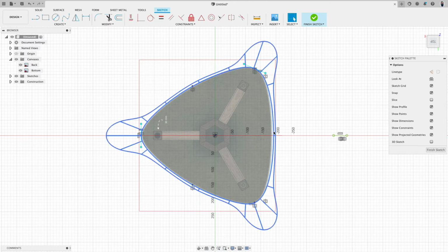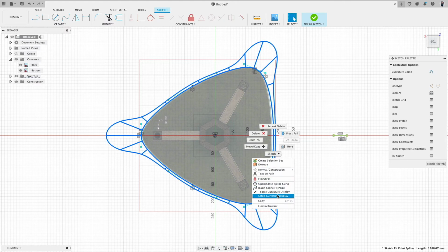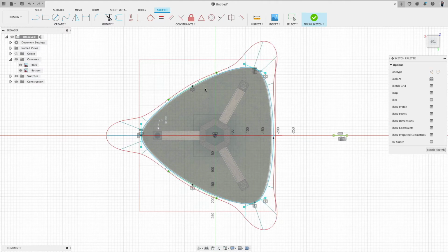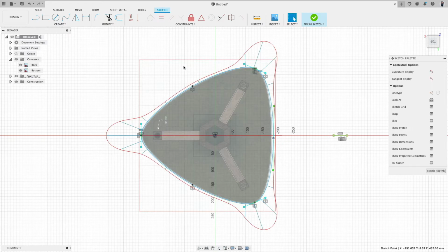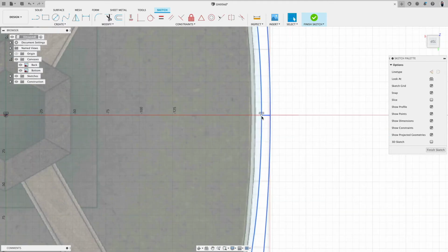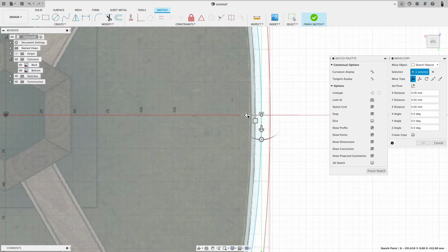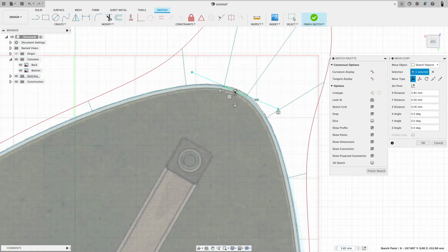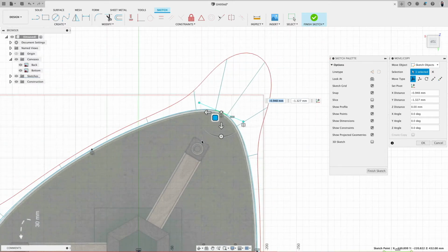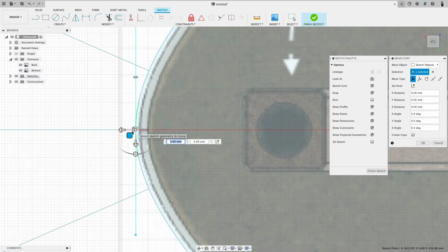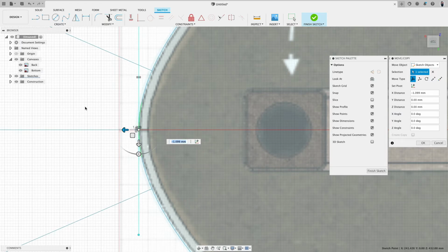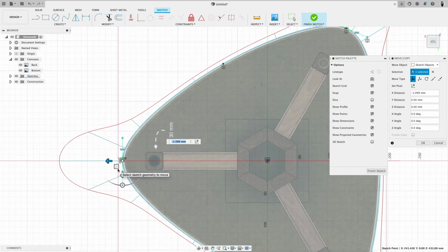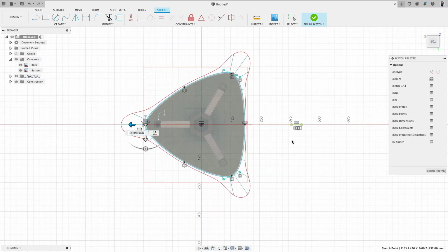Here, this is actually really good. I want maybe this to be a little bit closer. So insert fit point somewhere there, escape. This point horizontally constrained to here, escape, and then select the point M and bring it in. There we are. Maybe fine tune this a little bit. So you see, when you drag it this way, you actually do not snap to the grid. That's pretty good. Yeah, this is actually really good.